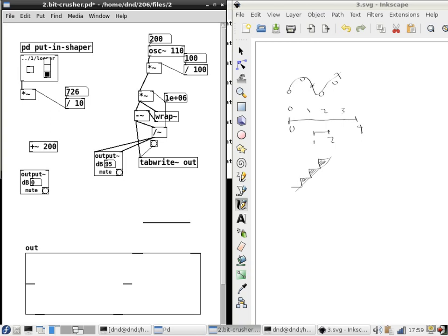Okay, now I've got my nice sinusoid, and in fact, if I look at what it is, you can't tell any difference because what's happening here is I'm making the thing be of amplitude 1,000,000, and then I'm bit crushing it so that it loses the fractional part, so it only has integers. But the integers, since they are on a range from -1,000,000 to 1,000,000, there's 2,000,000 of them. And so it's good to a part in 2,000,000. We're not going to ever hear the problem.